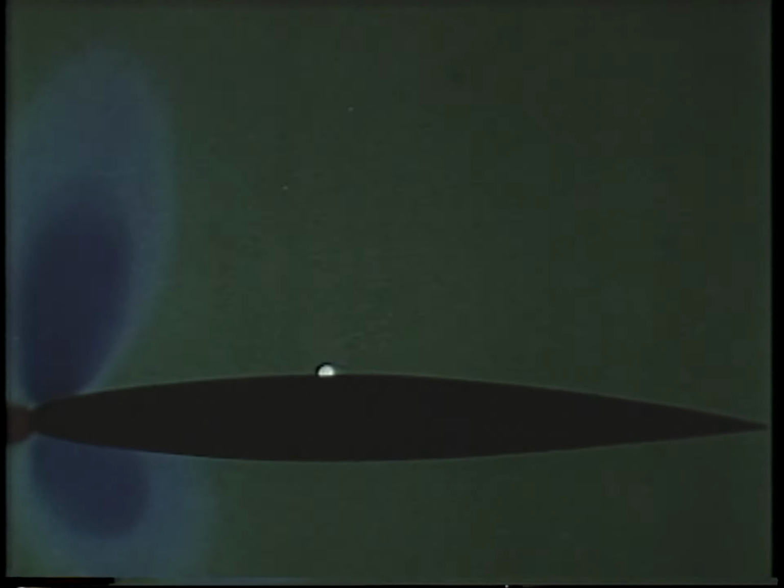Now look at a diagram. At the critical Mach number, the airflow is moving across the wing at this point at exactly the speed of sound. M equals 1. Above the critical Mach number, the point grows into an area in which the flow is faster than sound. M is greater than 1. Everywhere else, the flow is slower than sound. M is less than 1.